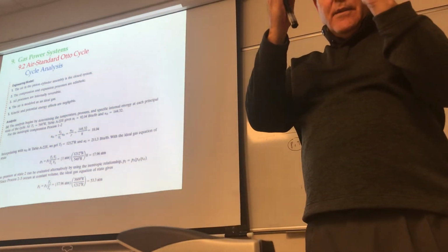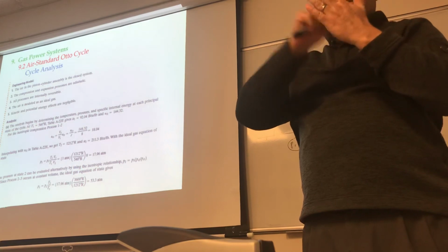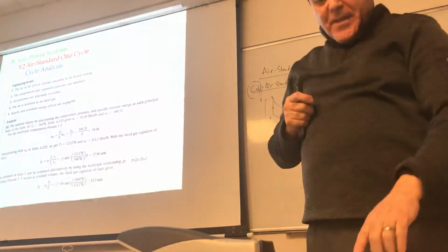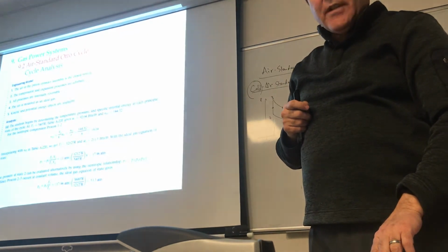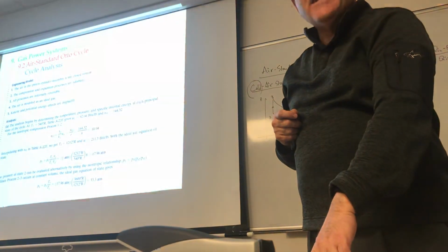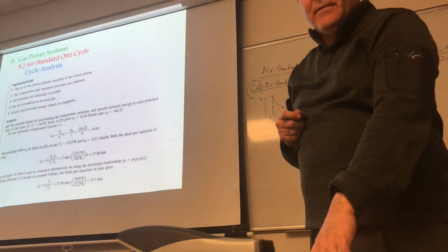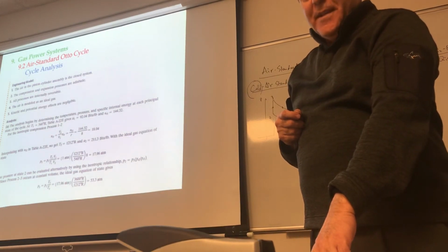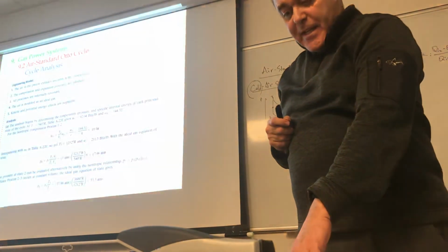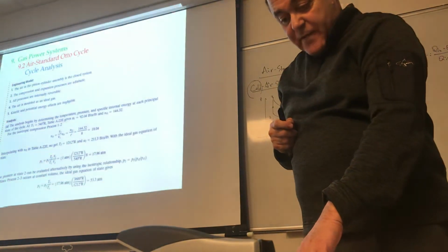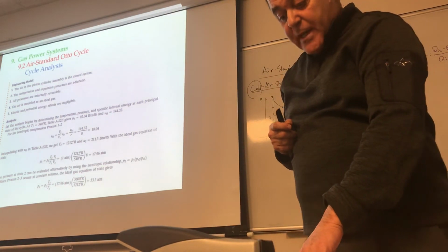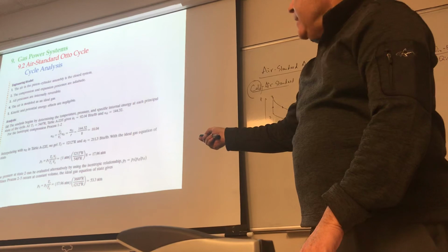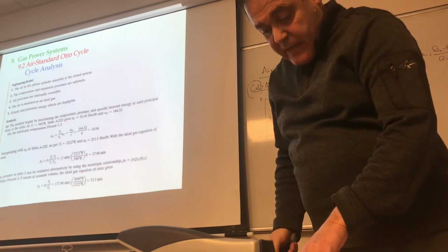So I always ask students to make a note of that, because you see, the temperature ends at 920, then it picks up at 940 on the top right. Don't say I didn't tell you. Because then I keep looking, what is vr? Vr on the top right starts at 3541. I keep going down and I'm searching for what? For 18.04. Where is 18.04?